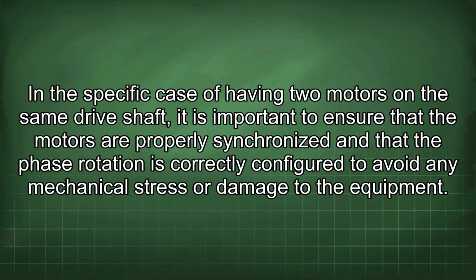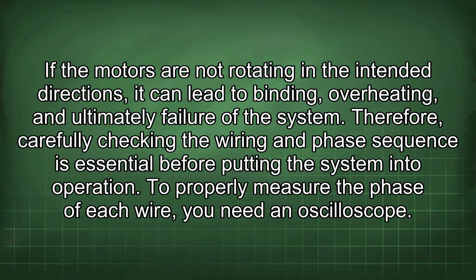In the specific case of having two motors on the same drive shaft, it is important to ensure that the motors are properly synchronized and that the phase rotation is correctly configured to avoid any mechanical stress or damage to the equipment. If the motors are not rotating in the intended directions, it can lead to binding, overheating, and ultimately failure of the system. Therefore, carefully checking the wiring and phase sequence is essential before putting the system into operation.